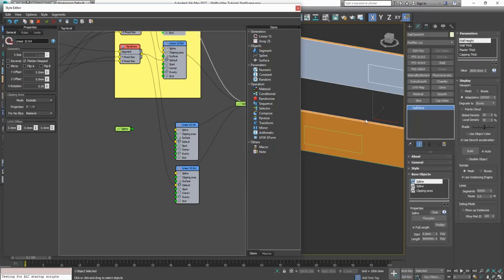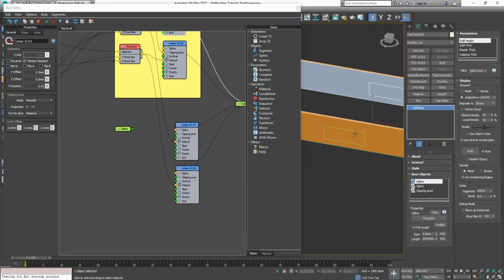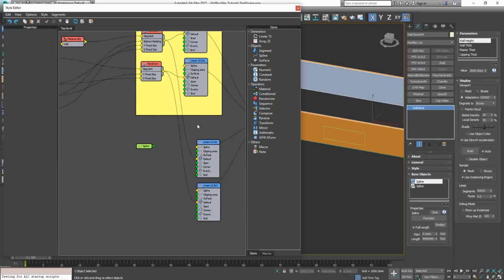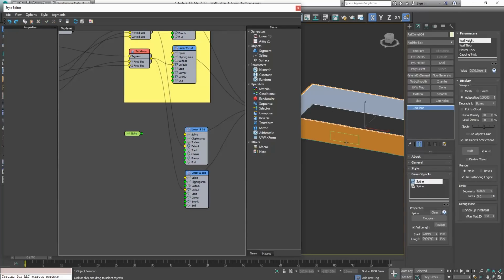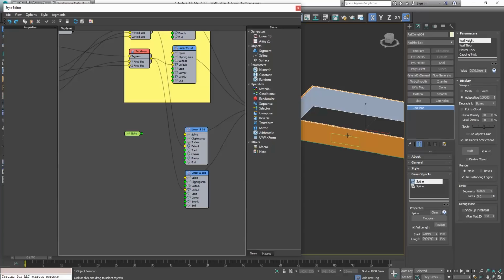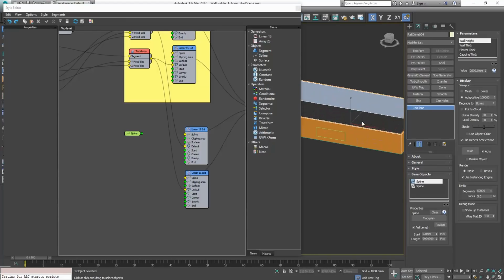Now, so that we don't cut a hole all the way through, what we're going to do is split up our sections into ID 2, 3, 4, 5, as the space spline is already ID 1. By doing this, when we cut a hole in this wall, it doesn't cut a hole in that wall, and for there and there.